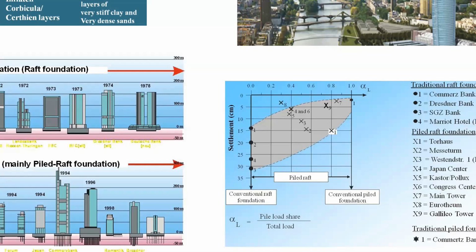And then comes the new generation where we have applied piled raft foundation, and you can see that by the idea of using piled raft foundation, we have controlled the settlement, and the maximum measured settlement was less than 15 centimeter. Also relatively higher than what we can imagine in other standards, but it's actually the basic idea that total settlement should not be our main problem.